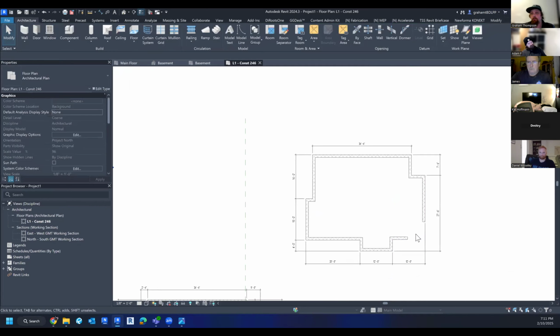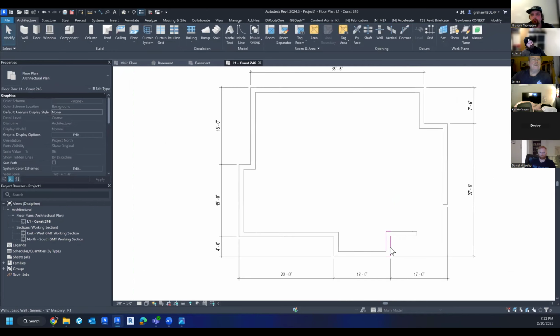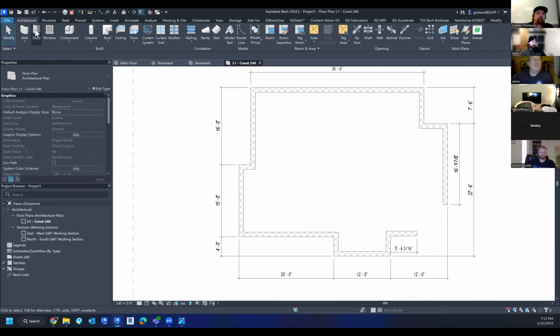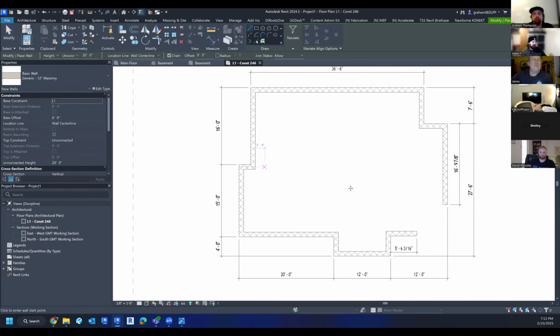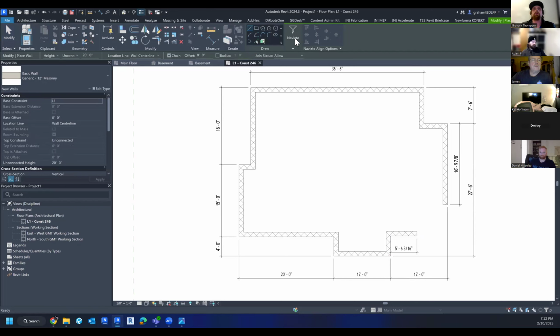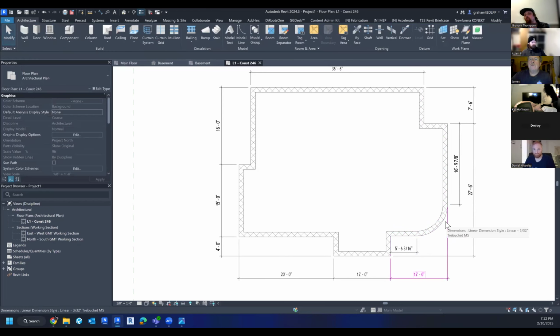And then last but not least, if you had something here, if I gave you these dimensions of where this arc started, you could just use a 3-point arc from here. 1 point, 2 point. Oh, sorry, I didn't click the wall. 3-point arc, 1 point, 2 point. And there's my third spot, right? So there's lots of ways to do that, okay?